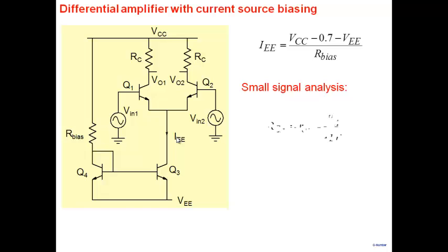All right. So what about small signal analysis? Under small signal condition, when I look down into my Q3, what do I see? When you look down, what does Q3 appear to you? R0? Because you're looking into the collector of Q3. Note that when you build the small signal model, what would this point be? Ground. This would be small signal ground. What would this be? Small signal ground here. So everything would be small signal ground. This would also be small signal ground.